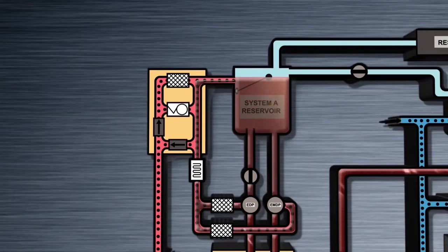The engine pumps are mechanically driven by the accessory gearbox on each engine, so the heat produced is negligible. The AC motors on the electric pumps produce a lot of heat by comparison, so the overheat warning system provides alerts to the flight crew when an overheat condition is sensed, but only for the electric pumps.